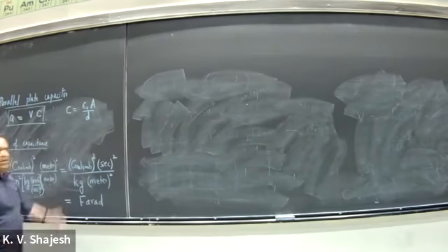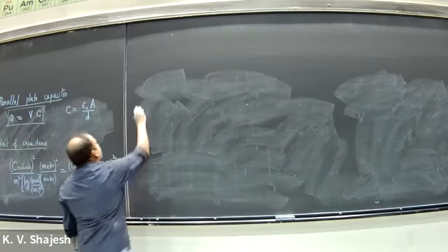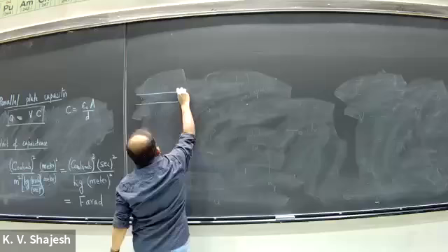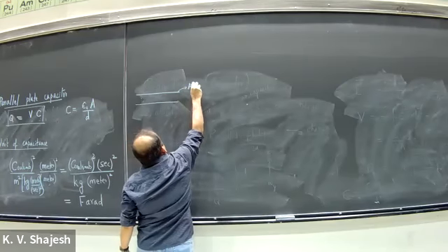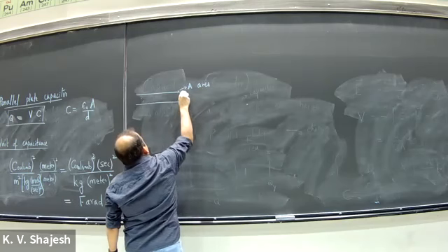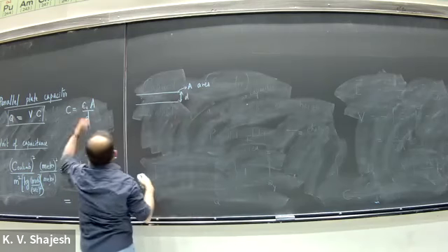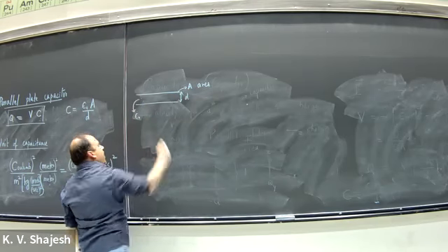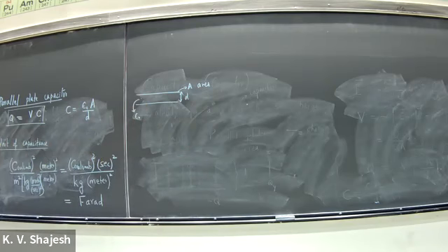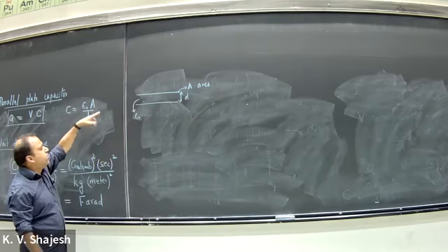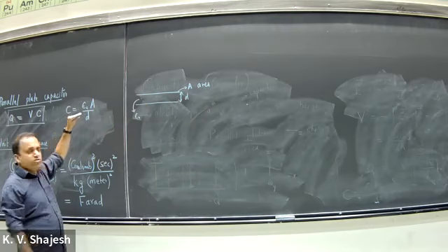So you want to create two parallel plates. So that's the capacitance, right? It has an area, A is the area, and that's the distance. And there is an epsilon also. So this is epsilon naught, right? If it is vacuum, that is epsilon naught. You want to build this. If you want more capacitance, then you need to increase your area, reduce the distance, right?